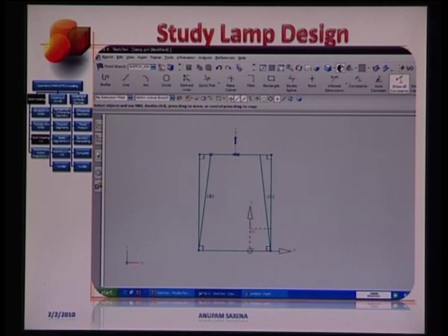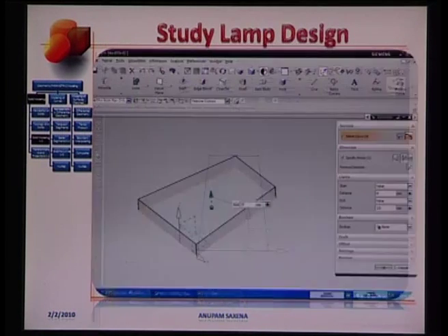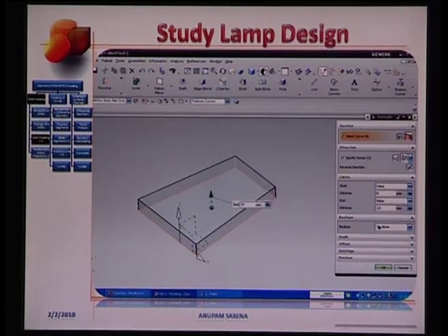First, the design of a base. We'd like to have a trapezoidal base. We carve this trapezoid from this rectangle here. We have a trapezoid now. We are going to be extruding this cross section into the third dimension, that is, the dimension towards 0, to get a solid feature. The height of this trapezoidal base is about 10 units.